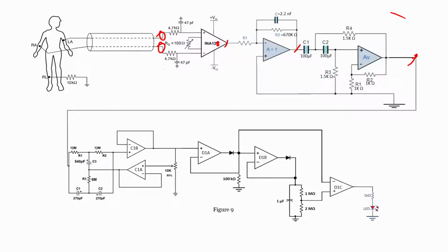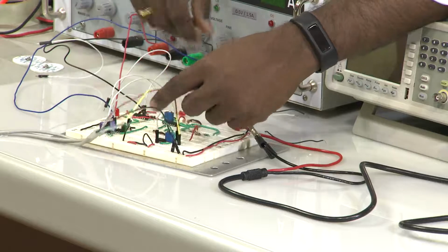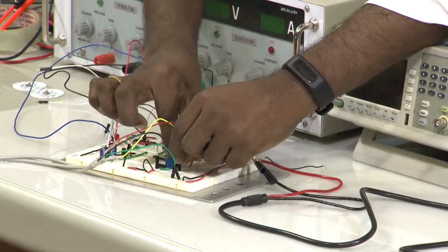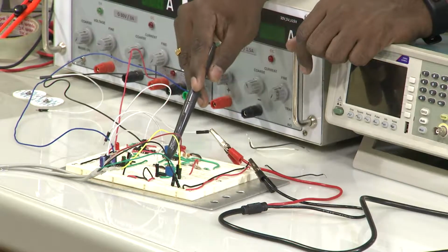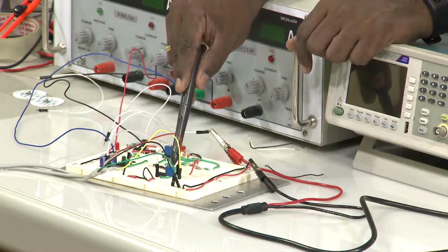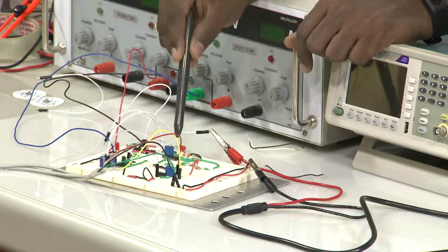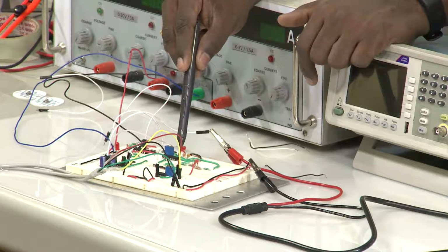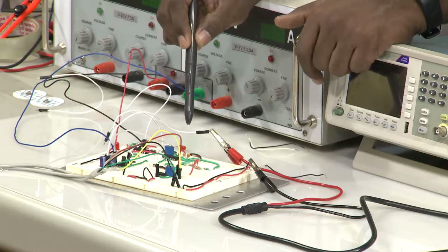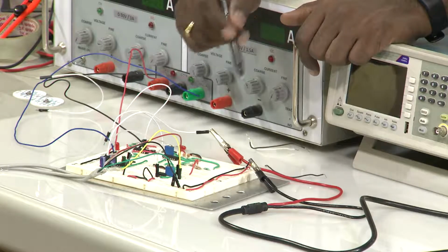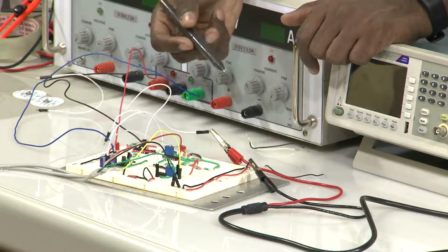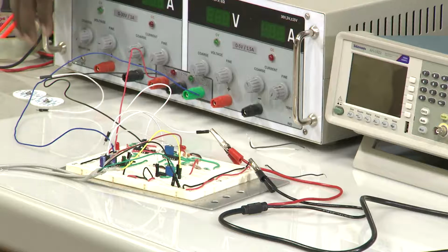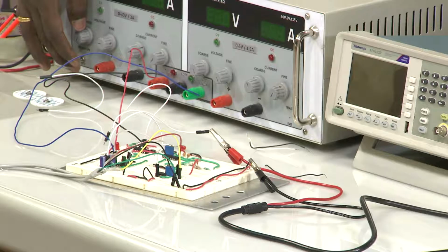When you see the breadboard, what I have done is the outputs of the ECG signal, through the leads, are connected to the inputs of the instrumentation amplifier. This particular blue color trimmer pot, which is a 200 ohm pot, we are using, and set it at 100 ohms, so that the gain will be as per the data sheet. You can calculate the gain of the system based upon the resistance that we have used, somewhere around 500 to 100,000 gain we are using. Let me switch on the power supply and we will see how exactly the signal will look.